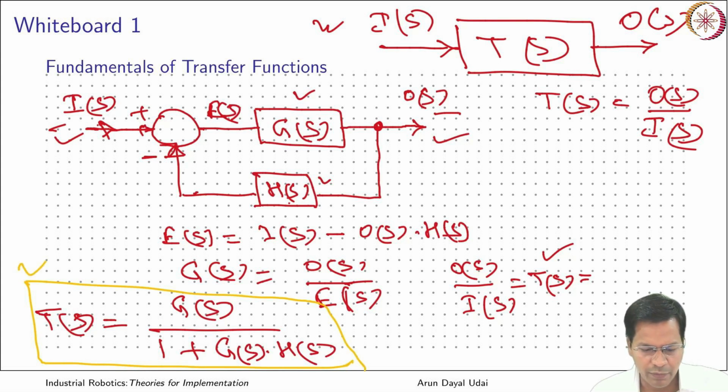Okay, so this is the reason I have discussed this in so much detail. So yes, this is your G(s) = G1 / (1 + G H(s)). The system structure is very much like this. There are many other transfer function rules, which I won't discuss here. But yes, this is how you can handle them in blocks. That is the beauty of arranging them in transfer functions.